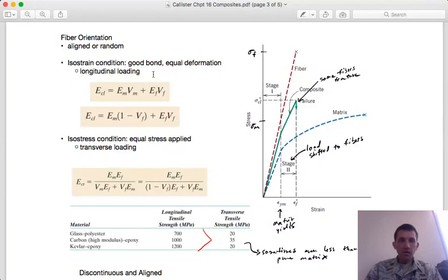And we see here in this stress-strain curve that you can see the individual responses of the components of the composite, and then the response of the composite itself. And like you'd expect from the rule of mixtures that we showed before with the upper and lower bound, the properties you get with the composite fall somewhere in between.